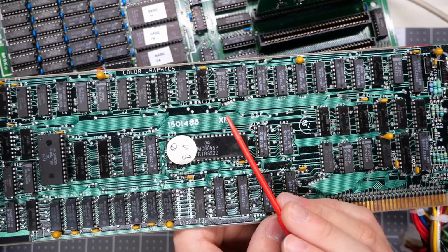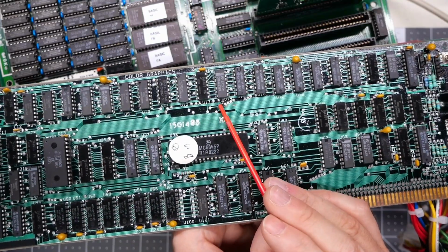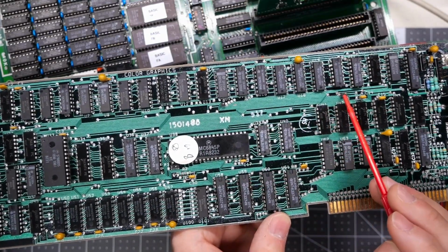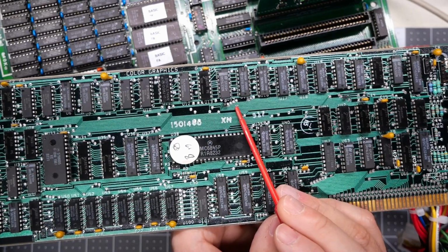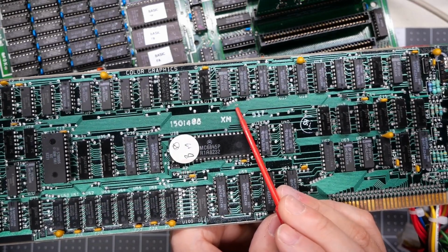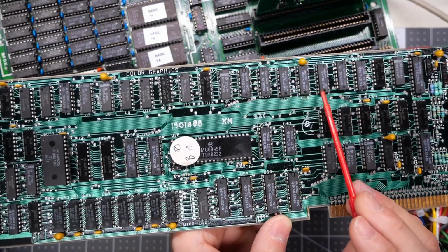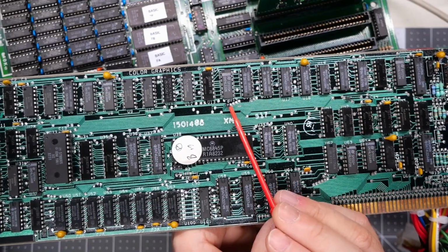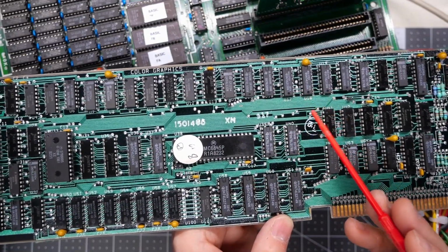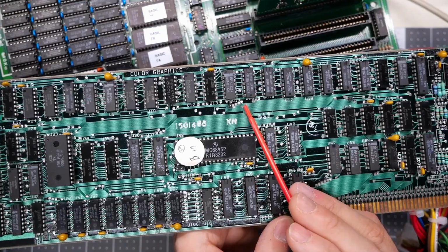Okay, so the mods are complete. I've gone ahead and installed a pin right there and right there so I can connect the jumper wire. And then I put a little tiny break in the trace right there. I can actually just bodge over that with a little blob of solder if I want to restore this back to the way it was. So if I just connect a DuPont lead between these 2 pins, that will have the effect of keeping this thing 100% stock. Or I could restore this.